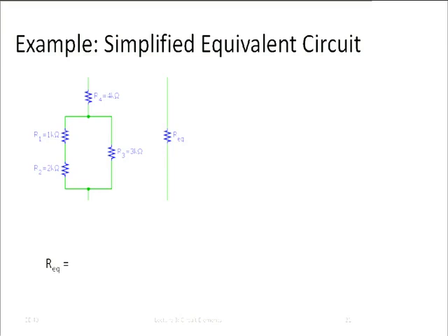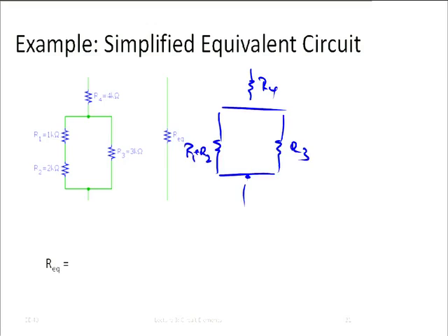So you can reduce the circuit to just R4, and here we have R3, and here we have to introduce some nomenclature. I make this R12, well, R1 and R2. Okay? Because they're in series, they simply add up. Now, what's the next thing we can simplify here? Okay, these are in parallel, so we can write R4, and so we have R1 plus R2 in parallel with R3.